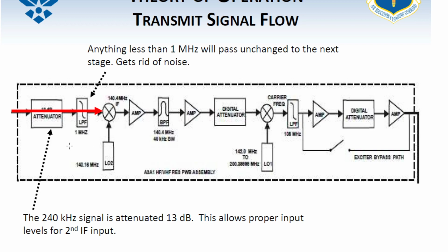So it doesn't stop it like a low pass filter, but it just brings it down. It just brings it down to the level it needs it at and allows things that are lower than a megahertz to pass through. So once it brings that two megahertz down to 1 or less, then it will pass it through. Correct. Absolutely. Sounds good, sir. That is absolutely correct.